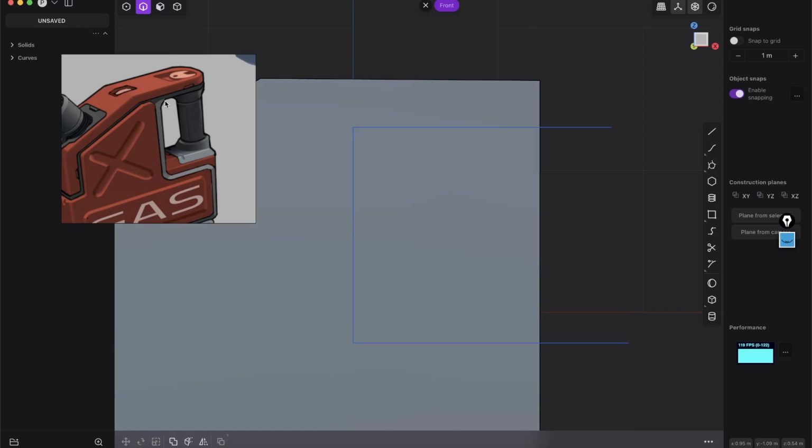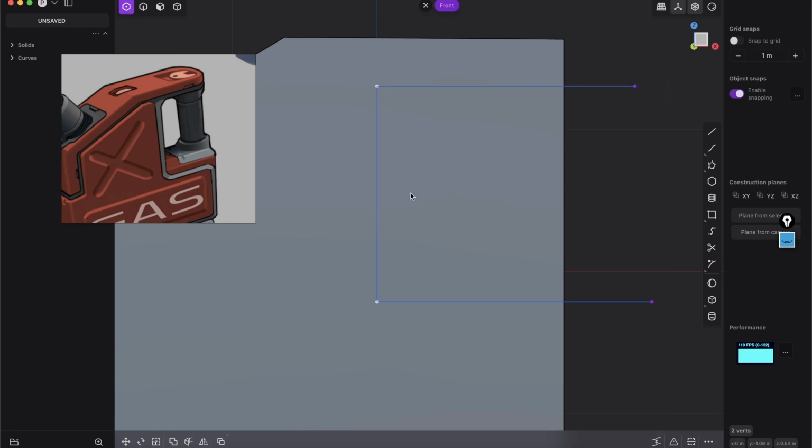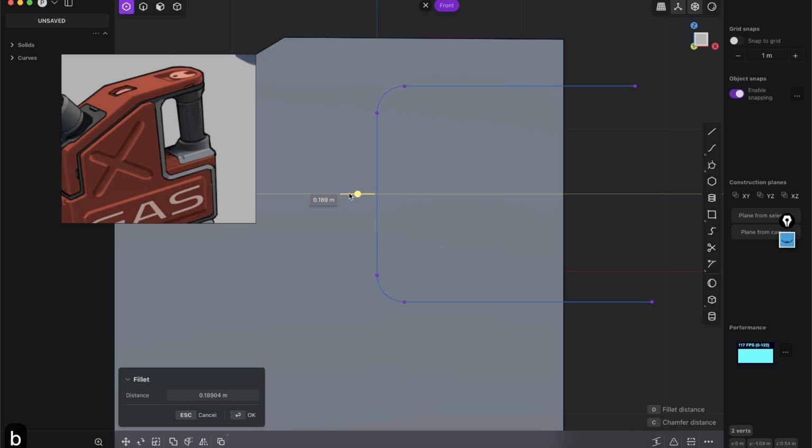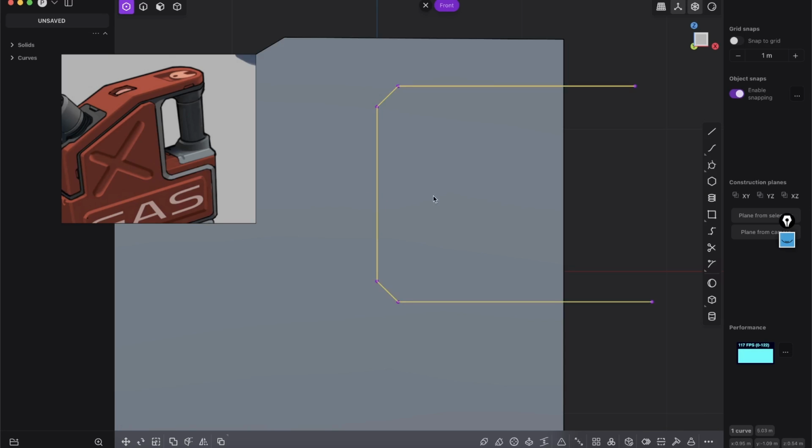And now let's give it a chamfer, and also here at the background. So if we want to give a corner a chamfer, we can press 1, and we will just select both of those points. And now here we have the fillet edge curve of vertex. It's on B, so you can just either click this icon or just press B. And if you drag it one side, you get the fillet, and the other side you get the chamfer. So very simple. And just press OK.